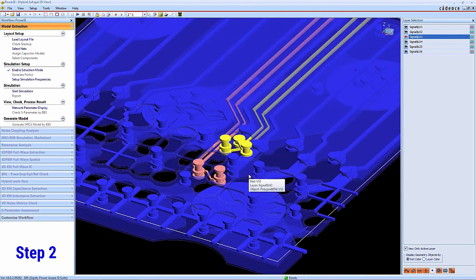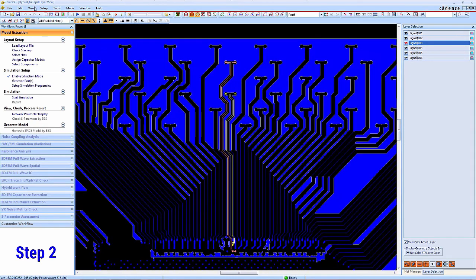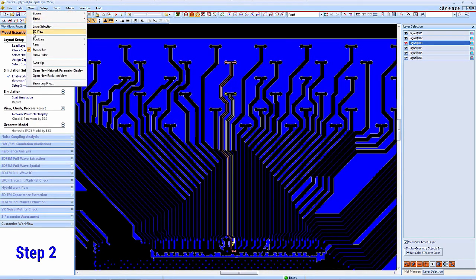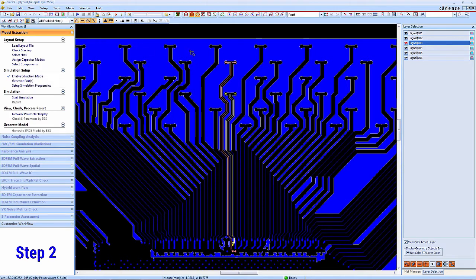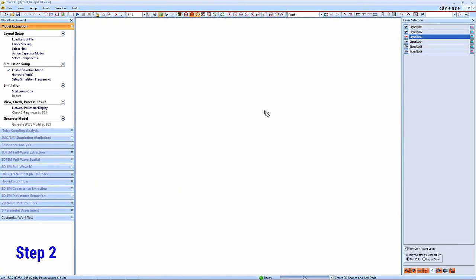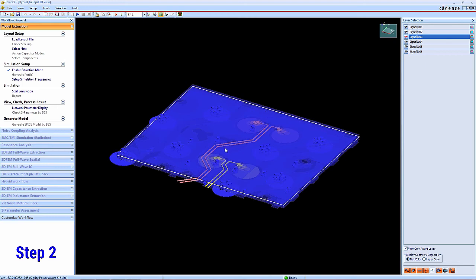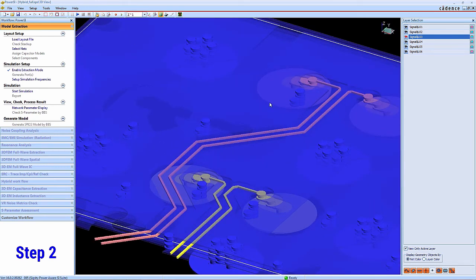You can see that I have return paths, but they're far from ideal. And that's the reason that this design was being considered for 3D simulation. Let's then go back and look at a 3D view of the board side transition. What you'll see is that we have fairly standard transitions. We have a large solder ball pad, interlayer transitions with vias, and then we have escape routing.